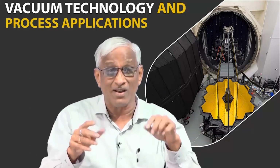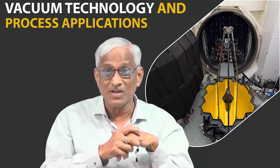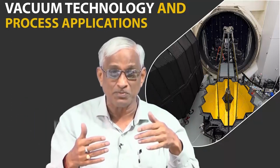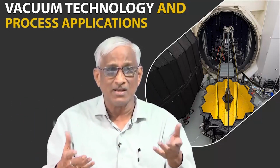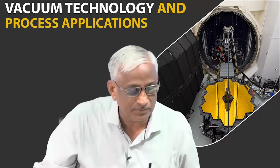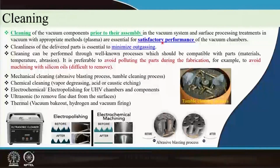Why? In vacuum technology, surface area matters, not only for joining and fabrication. The outgassing will be smaller if the effective area as seen by the vacuum chamber or pumps is less, because the specific outgassing rate is per unit area that matters. So, cleaning is very, very important.